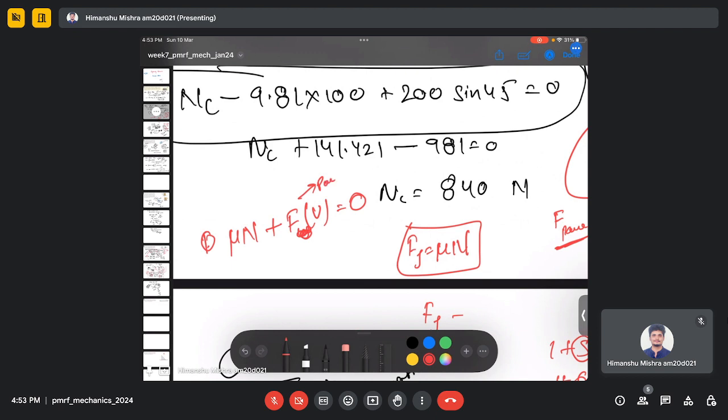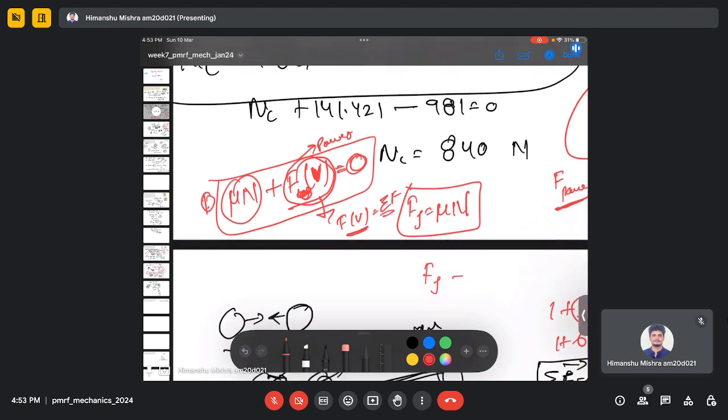Now this could be your power generating force, or this could be anything. Now you are changing this velocity. What is happening? This force term is changing, and in order to be force balanced, this force should also change, because this Fv is a summation of many forces. It could be a vertical force, it could be weight, it could be many forces which are acting on the system, and this change in Fv could change the vertical and horizontal components of force, which could change this N. So N in both the cases will be different.